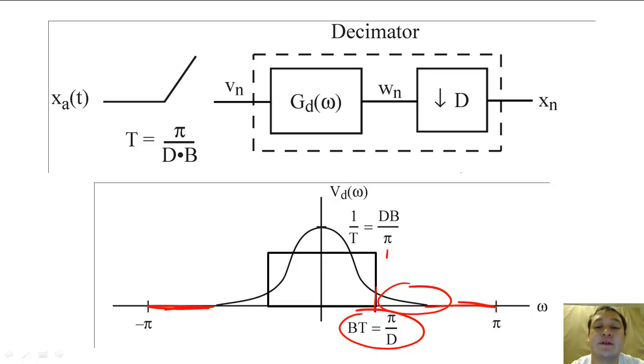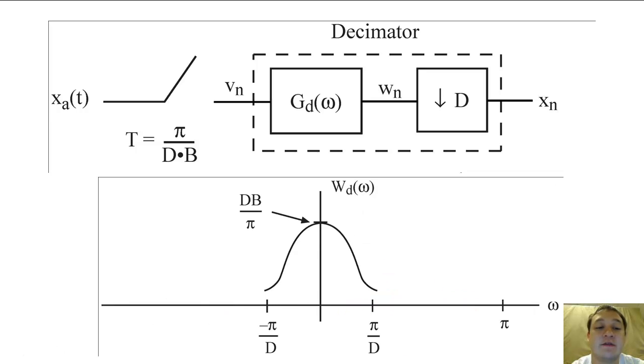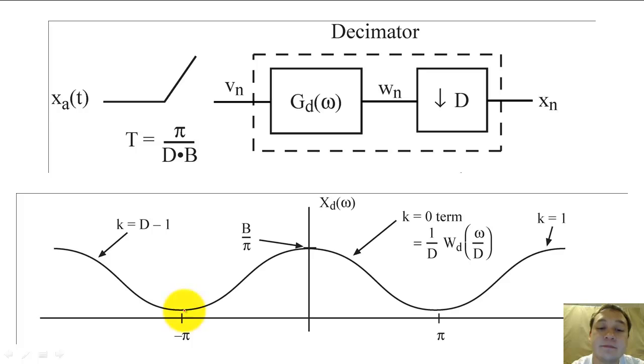After we apply the low-pass filter, the signal should abruptly reduce to 0 at the cutoff frequency. Therefore, when we downsample, we can stretch w_d so that the abrupt drop-off will now be at -pi and pi, and the function will look smooth because downsampling will produce replicates on either side. Notice also that downsampling reduces the magnitude of the DTFT by a factor of D.